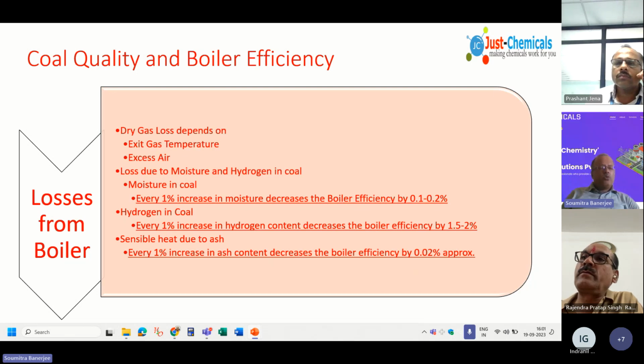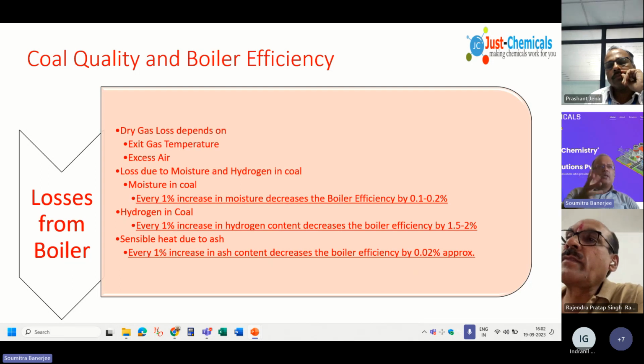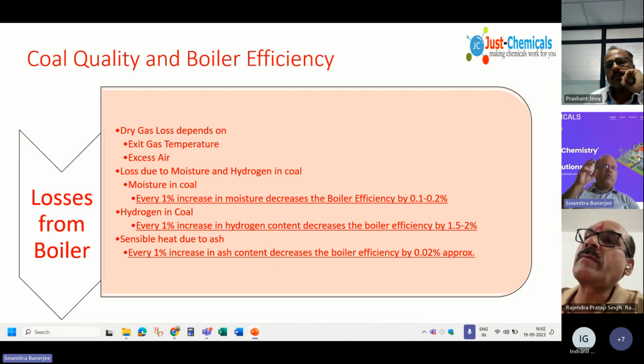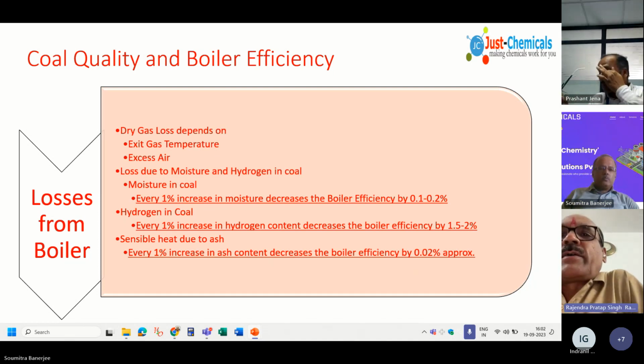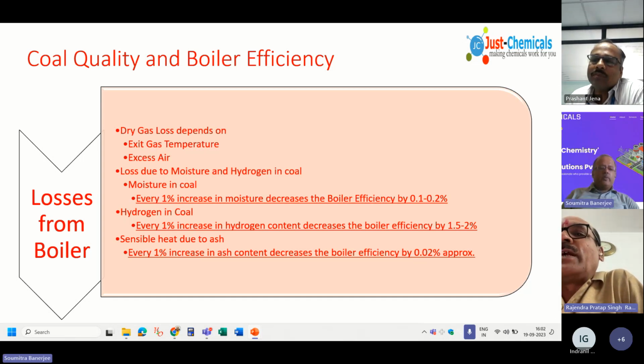If you have a single source of coal, then you may still go for once in a month. Otherwise, you may go for once in 15 days, a fortnight or so, so that you can compare when that coal, if you're doing it on FIFO basis, you know when you are burning that coal and when you are getting that sample analyzed outside. No, is FIFO used in our Indian context or what? Because it is not practical basically, I would say, because whenever.